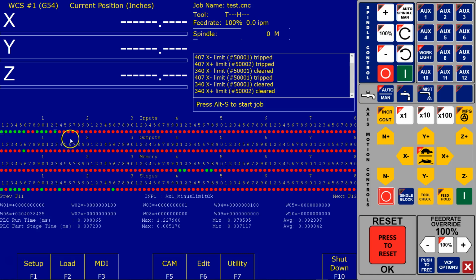All right. So, as you can see here, I have a little limit switch, and I'm just flipping the switches, and you see my inputs changing state as I flip them. Now, as you can also see, once I flipped various different ones, I started getting messages. For example, when I flipped number 9, I got this lube fault. And if I take a look, that's because number 9 is defined as my lube OK signal. And of course, when I flip number 10, my spindle inverter OK, I got this spindle fault.